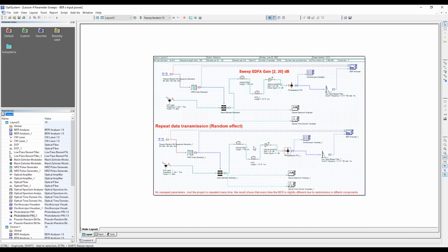So you can explore the different components in the library, which is in here. The bit error rate tester, the first connection is coming from the pseudo-random bit sequence, so you need to know what you sent. And then also the pulse generator, another line, and the last line is the output of the system. So the order of these things sometimes has to be clear, because if you mix them up, you might have a problem. You don't have any output at the bit error rate tester.